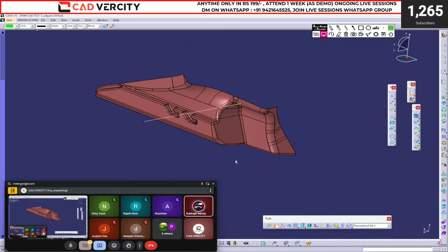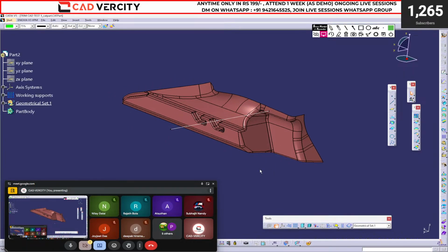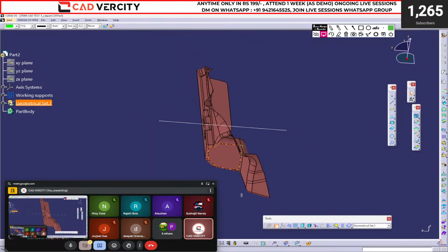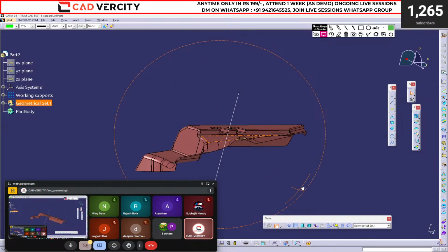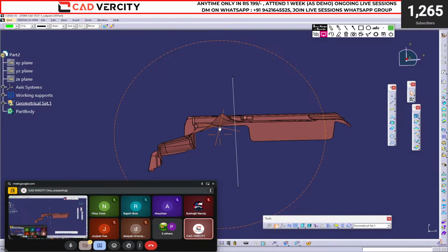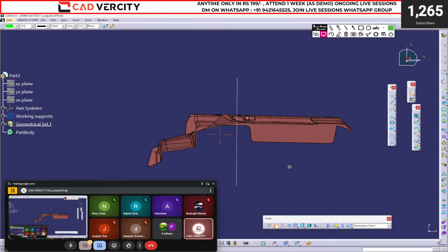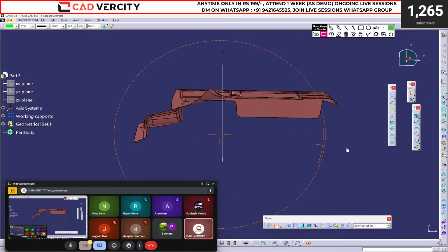Yes, sir. But tell me now, suppose you have the inputs in your presentation, you have to apply graining on this complete surface. Tell me in which direction your core and cavity will open. The tool will be something like this, yes or no? Yes, sir.